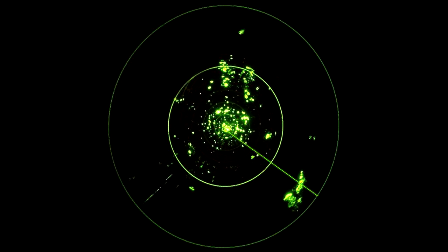When using primary surveillance radar, aircraft radar identification can be established by at least one of the following methods. Firstly, by correlating a particular radar position indication with an aircraft reporting its position over, or as bearing and distance from, a point displayed on the radar map, and by ascertaining that the track of the particular radar position is consistent with the aircraft path or reported heading.